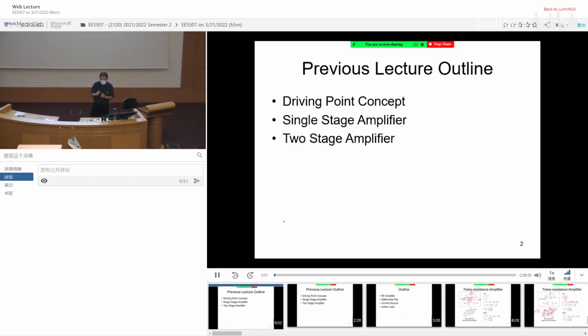Now, there are some circuits that are totally new, and you don't know how to approach them. If that is the case, you always have the fundamental. Fundamental means that you replace all the transistors with the hybrid pi model and derive everything. It's tedious, no doubt, but you only need to do it 10% of the time, so that is okay.